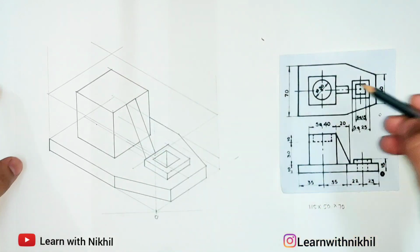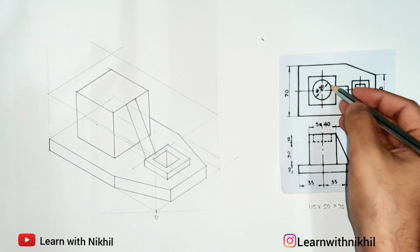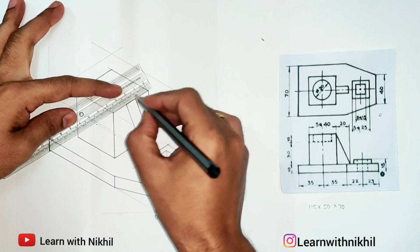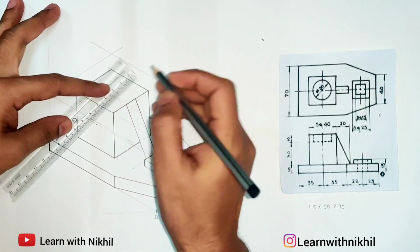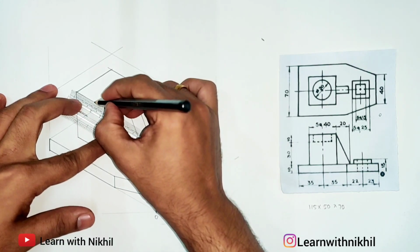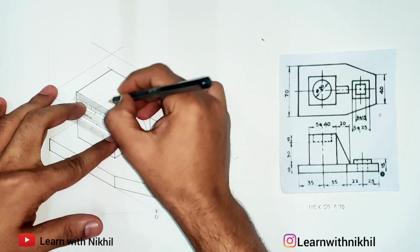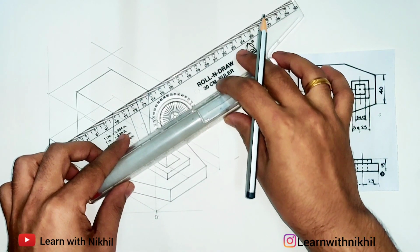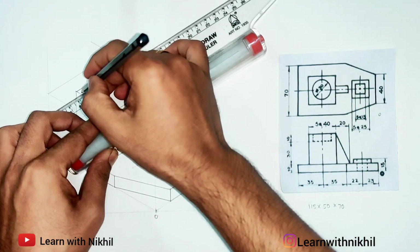Now here you have to create a circle of diameter 30. So already we have created a square of 40. So from the center 15 millimeter on both the sides I have marked the point. And on this side also from the center 15 millimeter on both the sides. So that will give me from the center the thickness of 30 millimeter. I'll draw light lines and create a square.